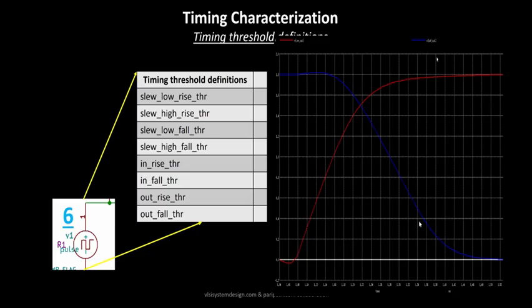For example, I had shown 2 inverters back to back. This is the input to the second inverter, and this is the output from the second inverter, so it's called inverter out. This is the output of the first inverter, which goes as an input to the second inverter, and we have written buffer out, which says this is the output of the buffer. We'll use these waveforms to understand the different syntax associated with the variables that you see on the screen.